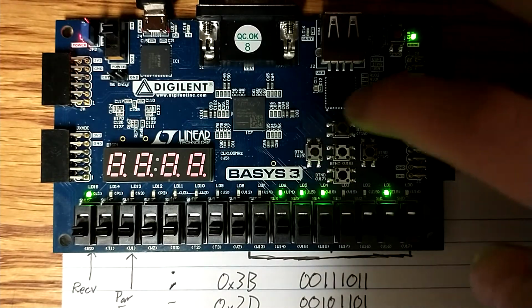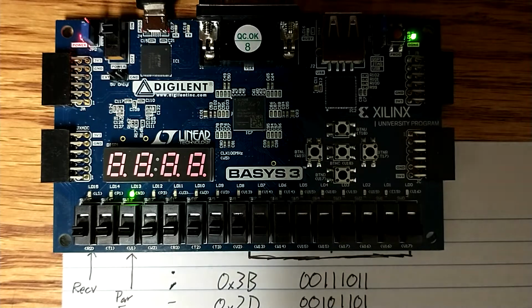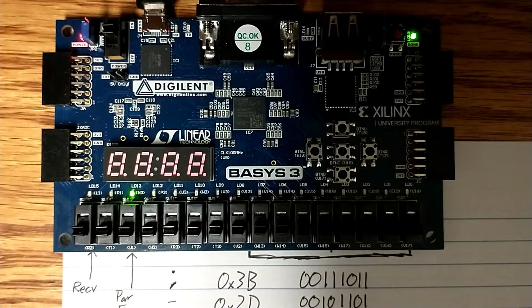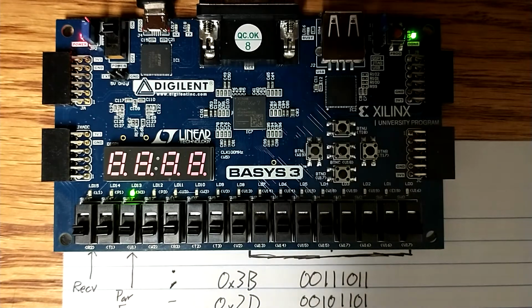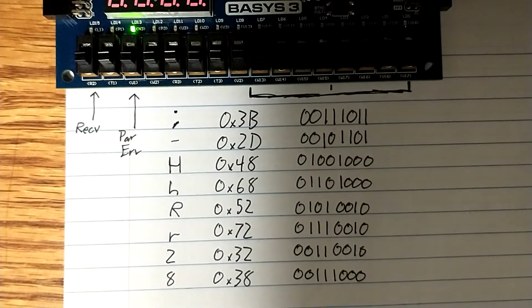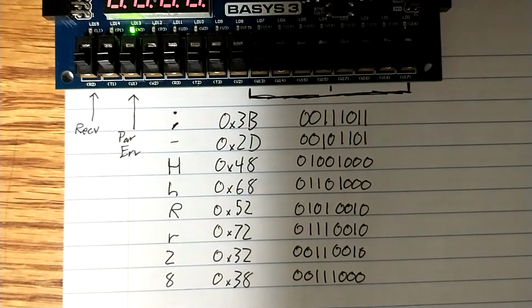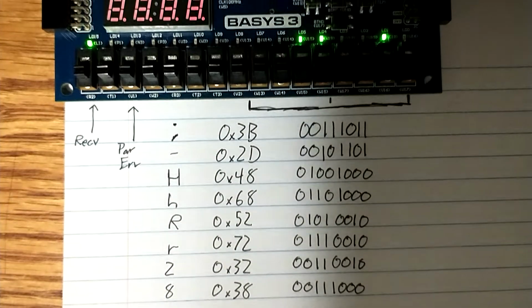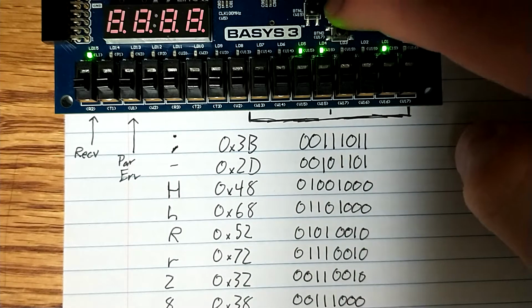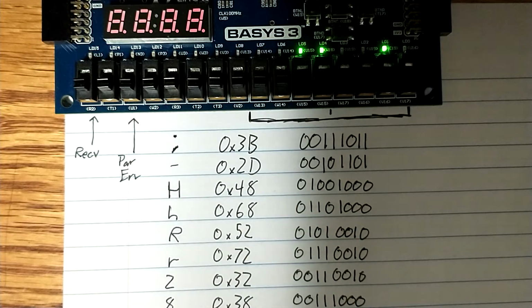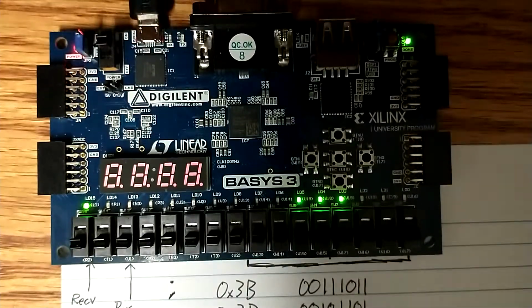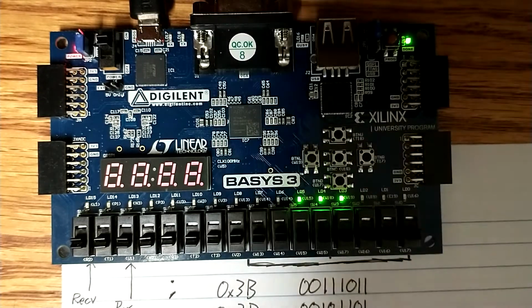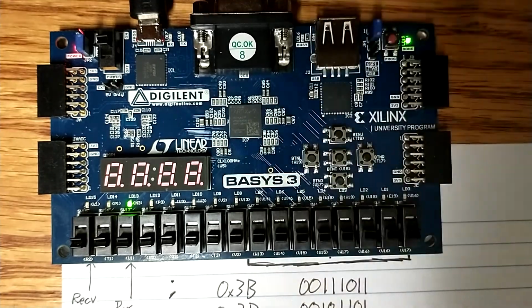See that example, and then we can also test the reset just to make sure that works. That reset sets the shift register back to 0, and we'll get that 0 output, and the parity error will go back high, since we're technically getting an even output. We can test it with a couple digits as well. Let's give it a 2, which will be a hex 3-2. Receive that, and then an 8, which will give us a hex 3-8. And send the receive on that, and we can reset.